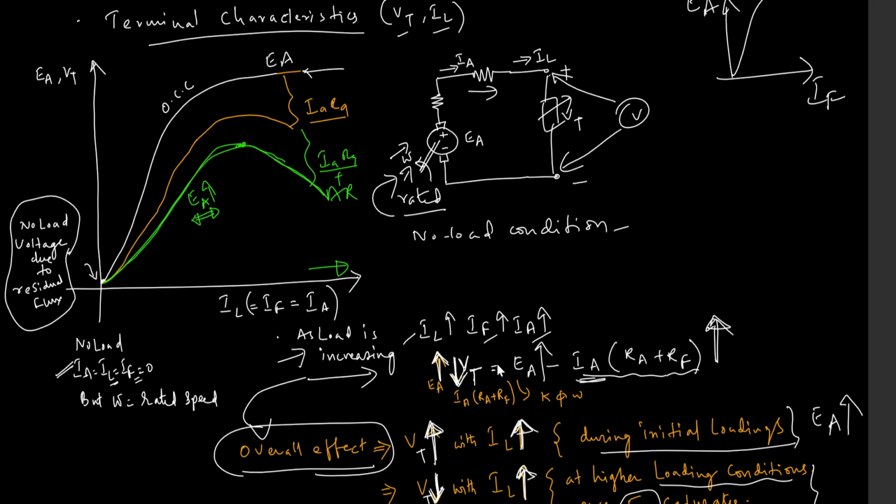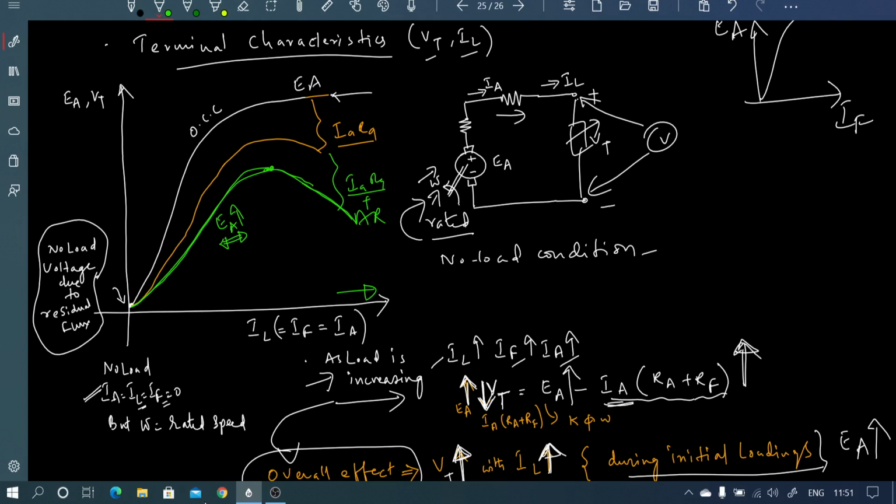So this is how the terminal voltage looks as compared to the shunt generators, where the characteristics are like this. The terminal voltage falls like this. Now here, depending upon the armature reaction effect and all that, the terminal voltage characteristics will be drooping like this. In this case, the voltage regulation is a positive voltage regulation, where the no load voltage is greater than the full load voltage, right? So that is why a positive regulation used to be there in the shunt generator.